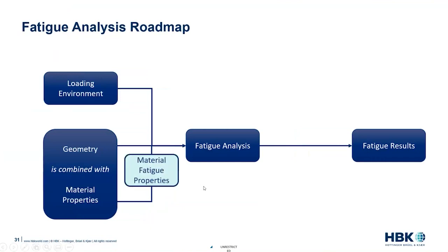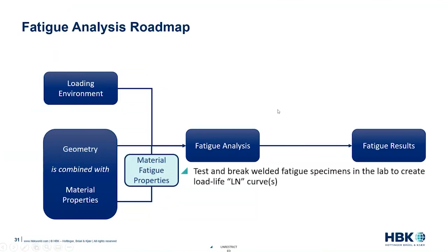So our material fatigue properties immediately start to include something about the particular geometry of that welded joint. So we test and break welded fatigue specimens in the lab to create a load life curve.